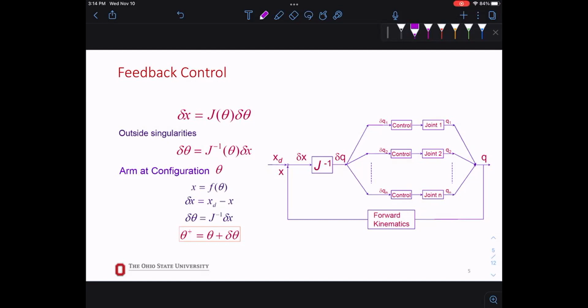So they all move together. You have 6 joints, so 6 DC motors, let's say. Now the first one has more effect on the robot. So when you're controlling, this is going to move the position of all of them already. Then you have to tune the second one based on the first one, and so it goes. You can't tune one by one, or you have to recalculate everything and then go to the next one, and the next one. Or you can have a vector and then develop an intelligent method to tune them together.